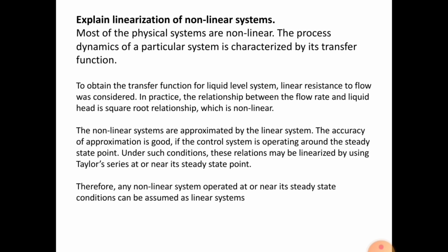And explain the linearization of a non-linear system. Generally most of the equations, most of the input functions will be in non-linear form, but to apply the Laplace transform we have to convert the non-linear equation into linear form by using a Taylor series. By applying a Taylor series we convert the non-linear function into a linear function, then we can apply the transform for that linear function.